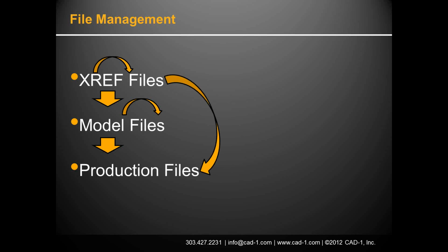One thing you do not do, you do not reference between production drawings. There is no reason to. You want to have this production drawing be unto itself. And what I highly recommend is the only thing you should ever put into a drawing is what is needed to create the drawing. If you don't need it to create that drawing, don't put it in the drawing. It'll make life so much easier.